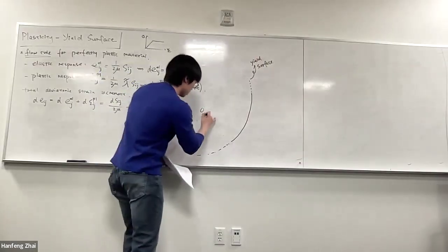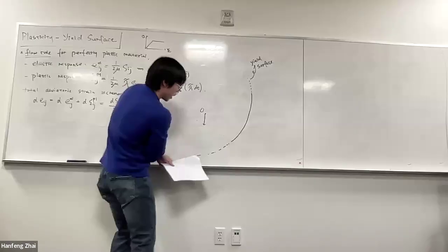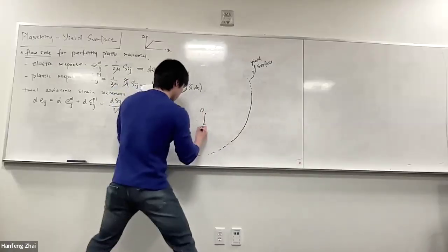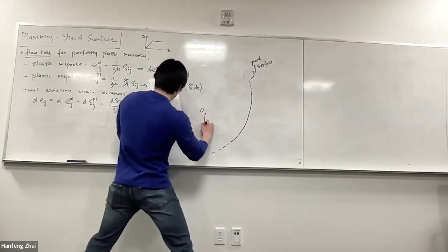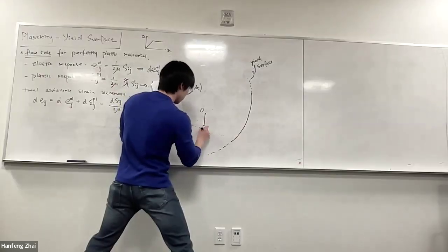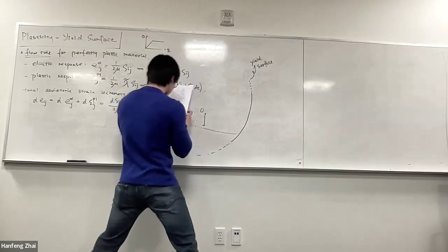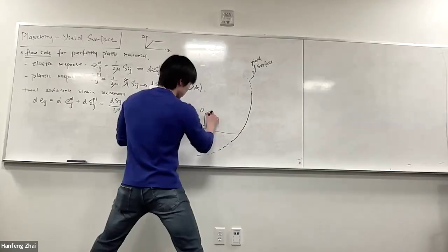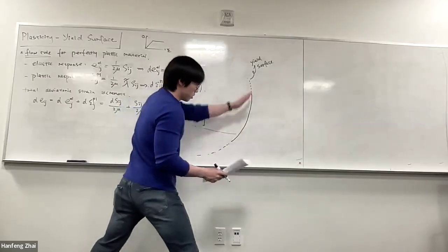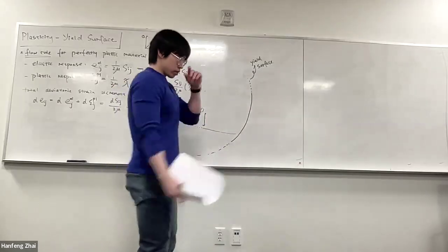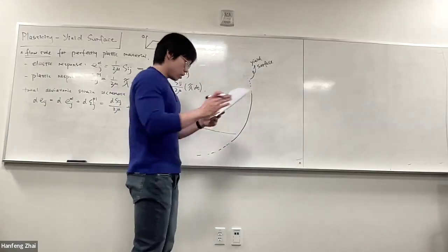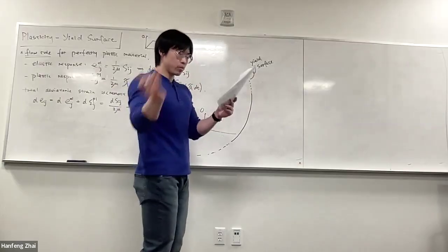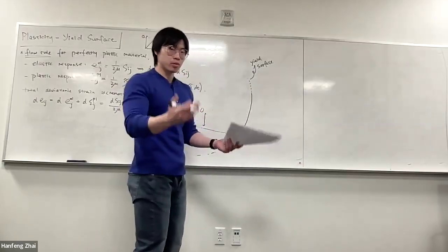And now let's say this stress passes through some Euclidean space, so your stress path. Before you reach the yield surface, you're in the elastic regime, where if you apply a stress, the corresponding strain path should be proportional, because it's elastic response or elastic deformation.